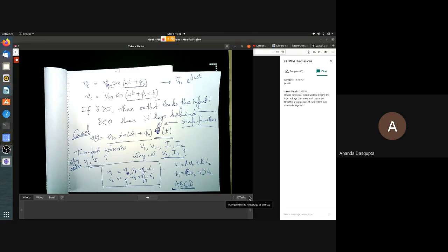There's one situation where this is used, which is when you try to describe transmission lines which carry power, for example, from the power station to your end. And the reason why you use these parameters for transmission lines is rather simple. If you think about it a bit, all the other parameters that we have talked about, Z parameters, Y, H, all of them need you to control both the input and the output. Okay? So either you take the input short, output open, and so on.